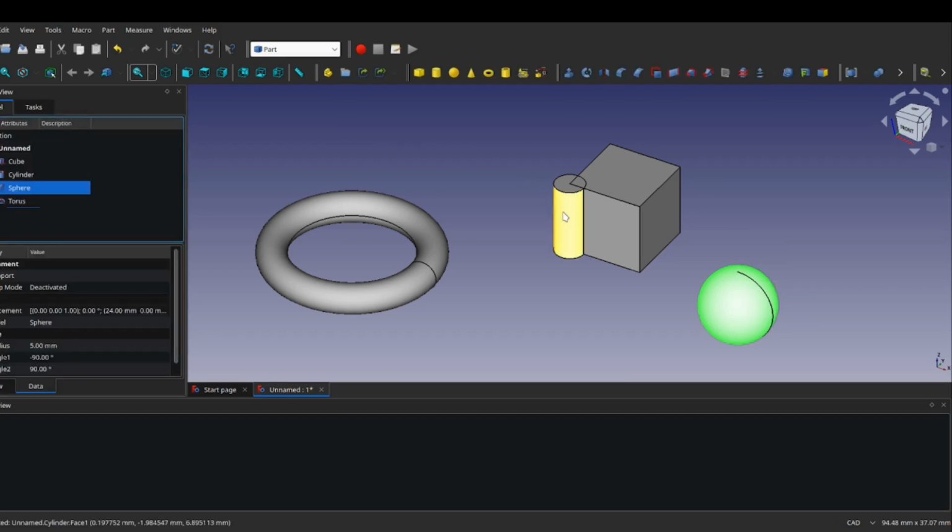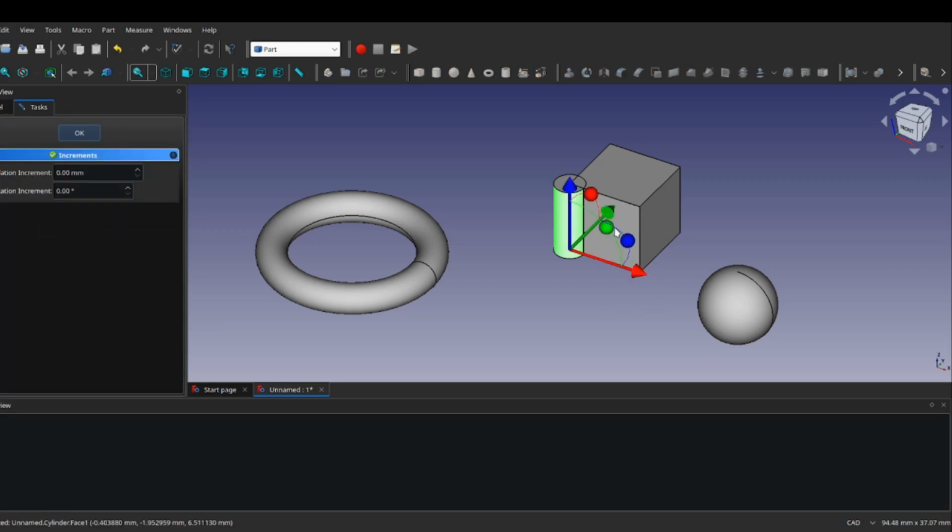Okay, I'm going to move my cylinder last. Then I'm going to get on to the part that was getting me about Freecad. That messed me up a lot about Freecad. But you know, when I was sleeping in the morning, the light went off. Oh, I understand why Freecad does that now. But let me move my cylinder. I'm going to go to Edit, Transform, and I'm going to move it down like this. So that's one thing I had to get used to going from a 3D modeler to Freecad, or probably any other CAD software. It would probably be like this for all of them. You have to go through the menu to move it.